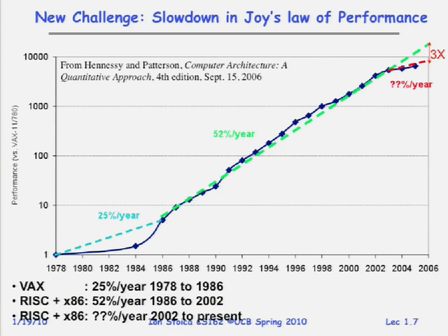Clearly, it has an impact, actually, about cost effectiveness and so forth. But I think it's starting from 130 nanometers. Well, 90 nanometers would be the first one, but they couldn't scale VDD down anymore after 130 nanometers, so the power density would go too high. The chips would just burn up. Yeah, so the big problem was the power. In order to scale the performance up, you need tremendous power.